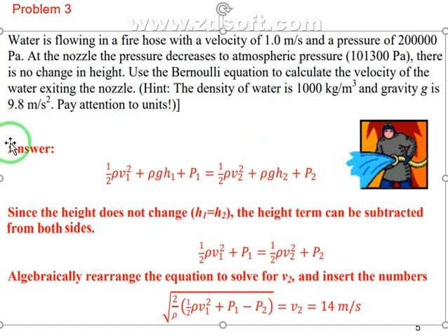So density, gravity, all these issues. So we apply Bernoulli equation. We know that Z with H, gauge with gauge. You see, we still have velocity here. We still have velocity at the nozzle and velocity at the fire water tank, right? So we're going to keep V1 and V2.